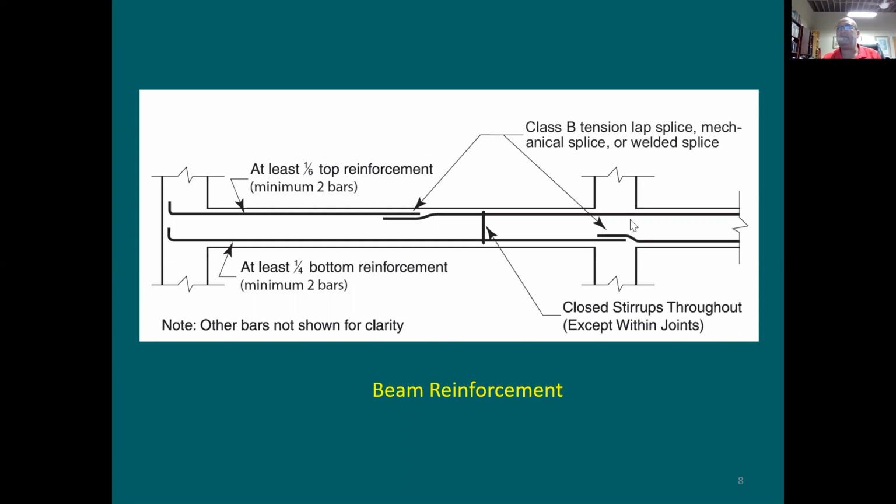And there are means and methods, some more analysis that you'd like. But if you have the choice, definitely splice the rebars in compression. Do not splice it in tension. This is gonna be the message out of this picture. We good? All right.